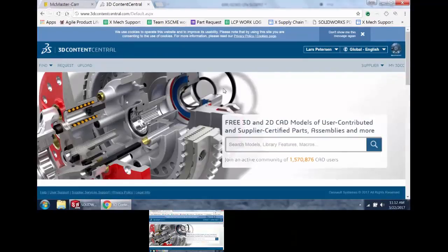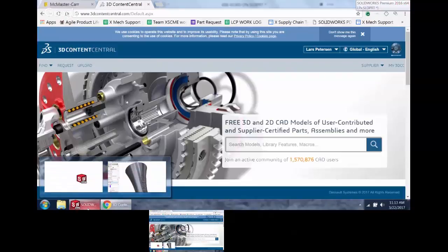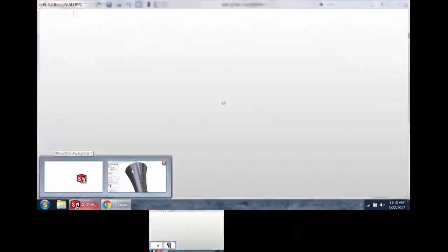Yes, sir. To cap that all off, when you initially did the extrude, didn't you just add your draft in there? I could have, but the surface doesn't work. Right, because the surface it's using is curved rather than planar. So if you choose a plane for your direction of extrude from the surface, it doesn't.